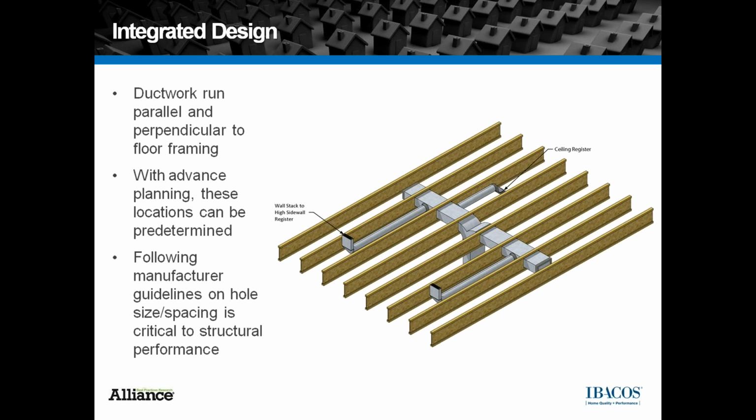Every time I look at this picture I don't like it, and now I know why. It dawned on me. We're talking about having short duct runs. In the perspective you have here, it looks like the duct is right up to the edge of the floor joist, but in perspective, if that's a 10-inch floor joist, that's not a very long duct run. So we're talking about making space within the floor system to run your ductwork in there.